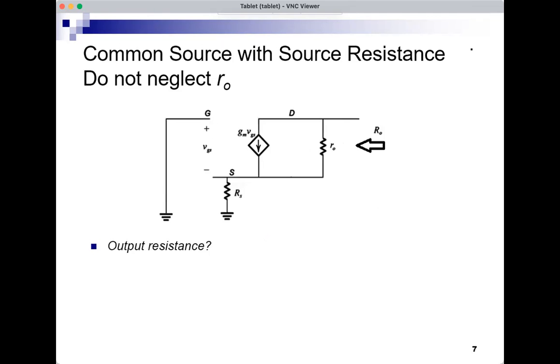So this is the circuit with VI 0. And again, I'm applying the definition. VI is 0. RO, this is our I here with our test source connected here. We test, and I want to find I test, and then calculate the ratio V test over I test when I disconnect the load and replace it with the test source, and I set the input to 0.